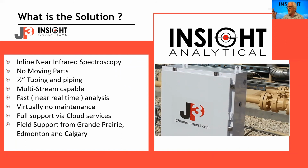The big advantages are no moving parts. Everything runs through half-inch tubing and piping. It doesn't plug off very easily like the eighth-inch stuff does. Fully capable of monitoring multiple streams in a facility. Very fast analysis, near real time. It can get down to be as low as about 15 seconds for a data update. Virtually no maintenance. I mean, having no moving parts and large diameter tubing eliminates a lot of the maintenance issues.